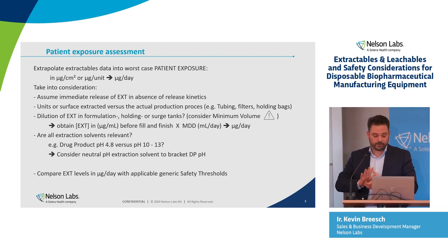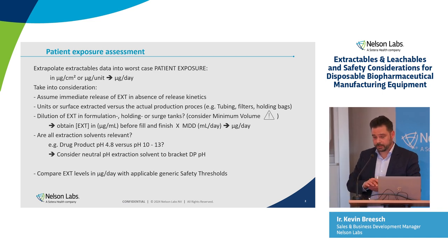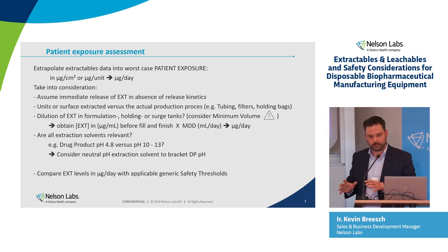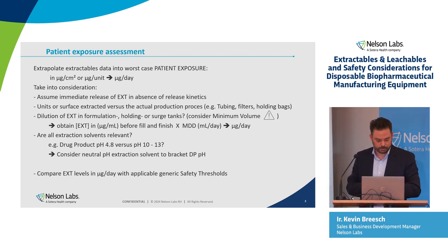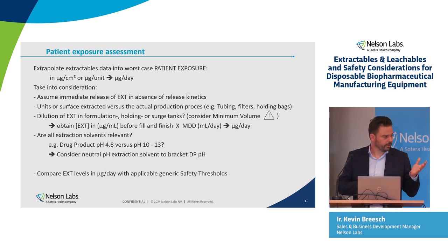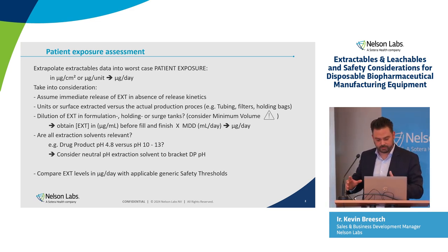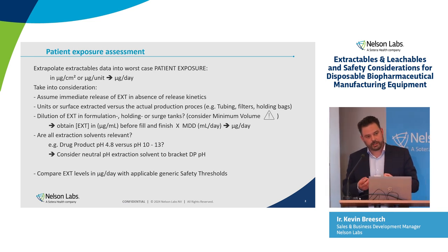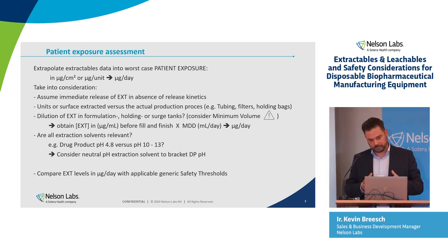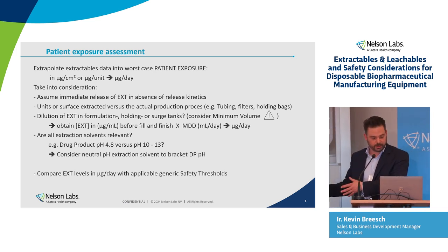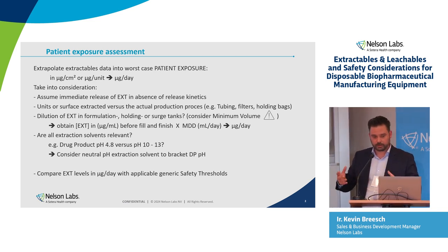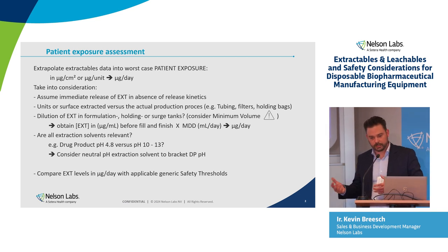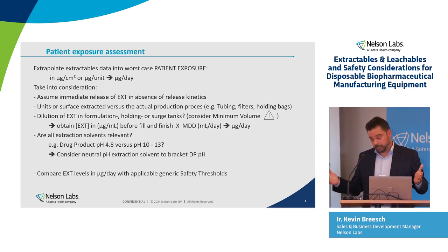Are all extraction solvents relevant? That's also an assessment you can make. Typically we do that for medical devices, but that knowledge you can also apply for extraction of single-use systems. And the question was raised, I believe, yesterday, pH 10 versus 13. In the end, you want to have a predictable extractables data set which is reasonable to become a leachable. So, for instance, if you see at a very high pH of a filter polycarbonate housing, you see bisphenol A coming out, which you should be considering then.